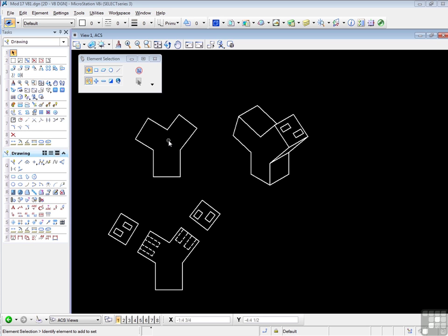The end result of the exercise will be as shown below, where we see the two auxiliary views of the left and right arms of this object, together with the hidden information for the holes. The point of the exercise then is that the auxiliary views are difficult to draw since they are angled projections of the object's two arms. However, if you create an ACS for each arm, the two auxiliary views become very easy to build. So if you would draw that front view first, then we can begin.